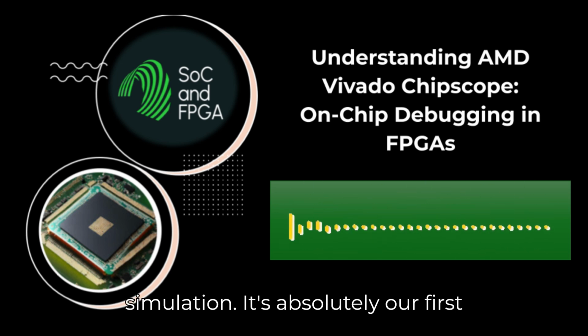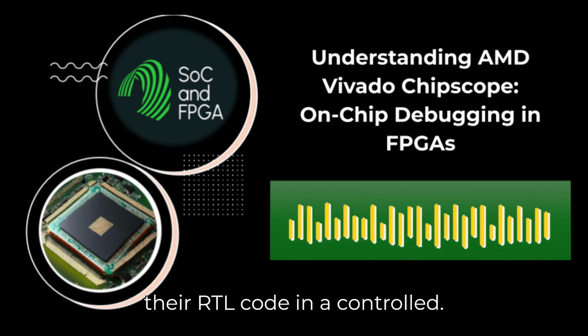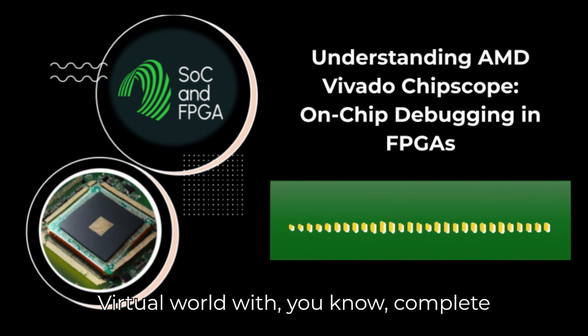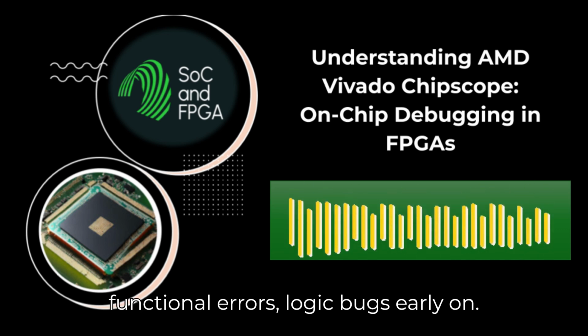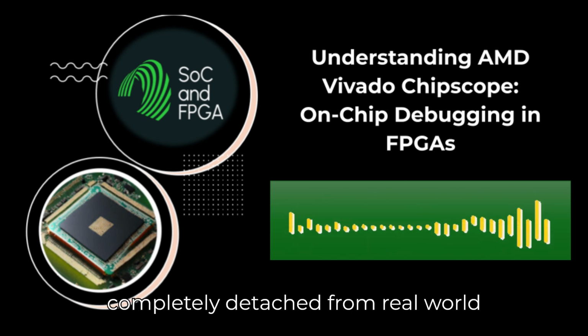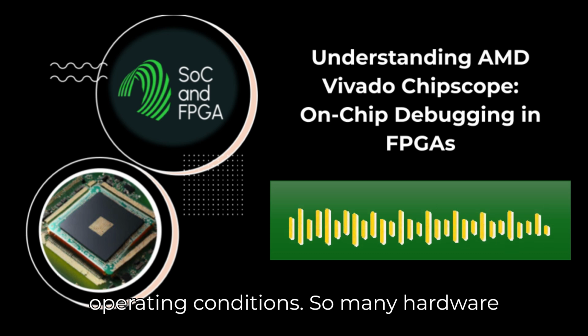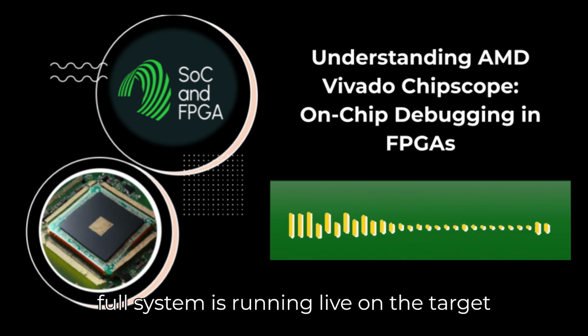Well, take simulation. It's absolutely our first line of defense. It lets designers test their RTL code in a controlled, virtual world with complete visibility. It's excellent for catching functional errors, logic bugs early on. But its main limitation is that it's completely detached from real-world operating conditions. So many hardware issues appear only when the full system is running live on the target board.